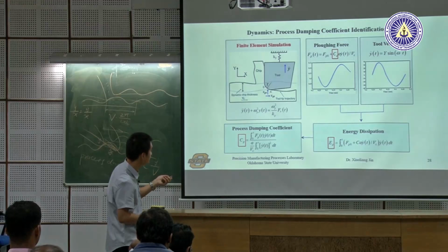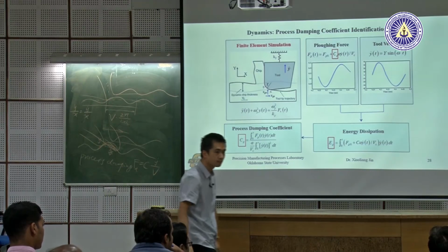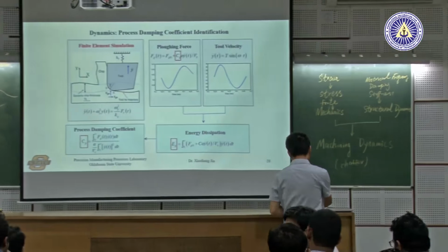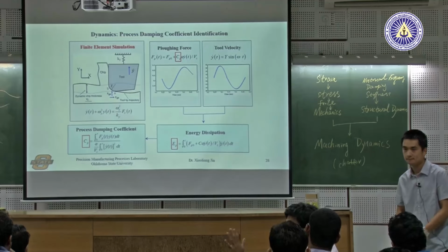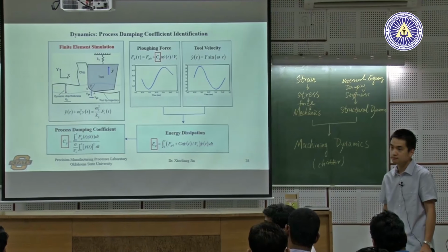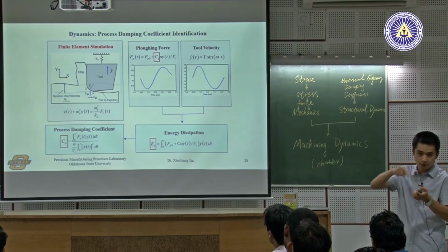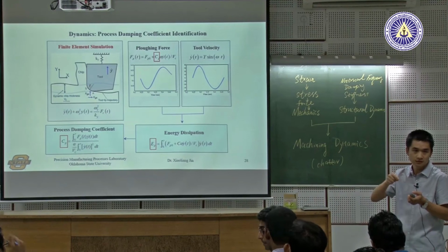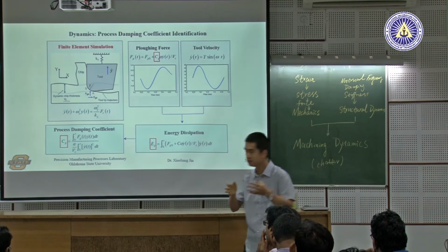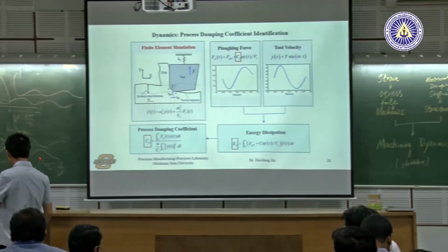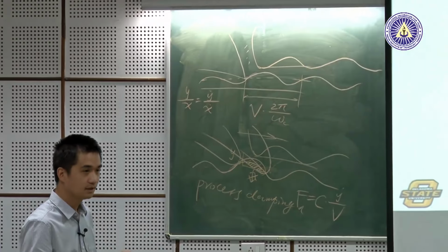So that's some details about that, but here's the general idea. Just one point: this mechanism is not unique to only micro milling. It also happens at macro scale. We did not discuss this yesterday because non-linearity is left for today. For a conventional machine, if the tool gets blunt and has a very shallow flank angle, what happens to the wave if the speed goes down?